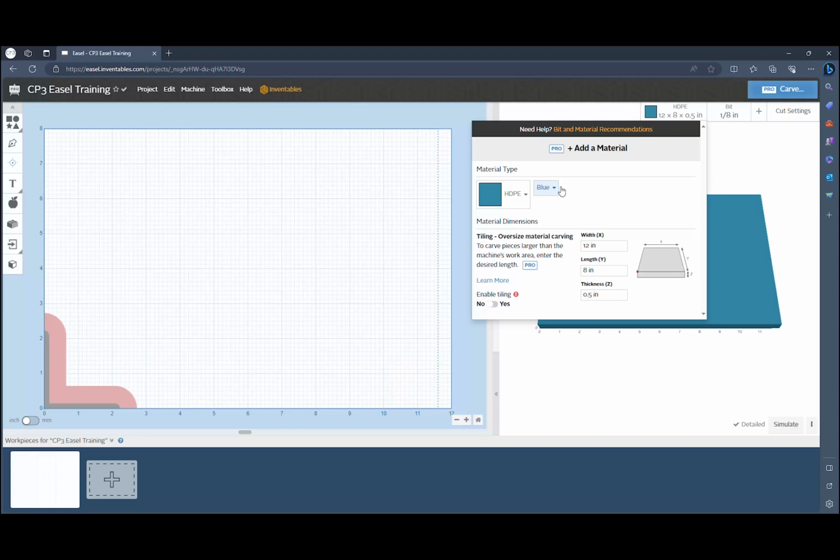So yeah, I'm gonna cut a sheet of 12 inches by 8 inches. It's already in there. This is the maximum size of the sheet we can fit in our CNC machine. For the thickness, it's gonna be 1/8 of an inch. Enter. Here we go. And there's also this button in the bottom corner to switch from inches to millimeters, whatever you're more comfortable with.